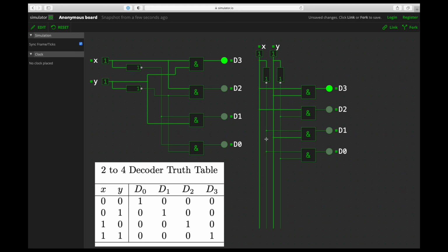So you'll always have typically all combinations of input lines available to you, and then you just make this matrix of connections that you will need from the truth table that you just constructed. It's a relatively straightforward process, and as I always mentioned in class, this is not hard, just tedious. Of course, then we have tools to minimize the truth table before we implement the wiring. But even after that, we just look at the truth table, make the connections, and it's so simple that a computer can do it, and that's exactly what we have.